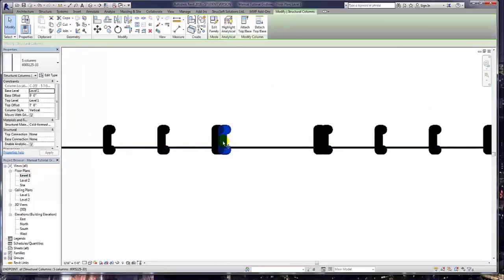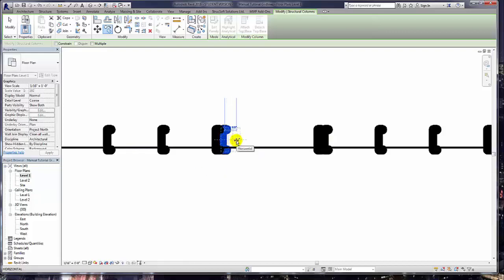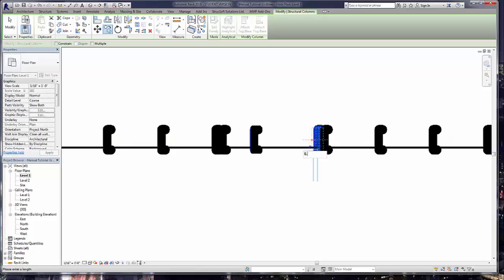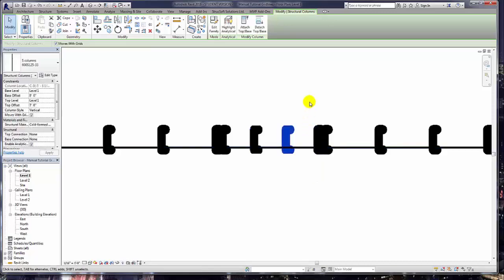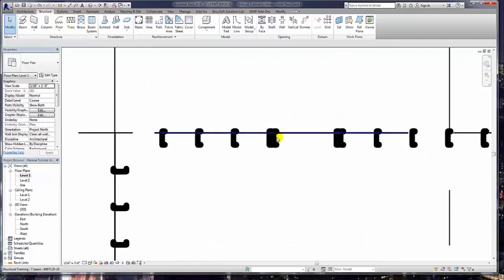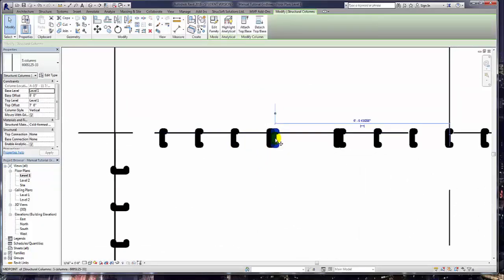Next, copy the jack studs, the ones that we just created, on the south side of the structure and place the copy toward the center of the door frame. They should be placed a distance of 0.7767 foot away. It's approximately 9 1/3 of an inch. Take the same steps for the north face of the structure's door opening.